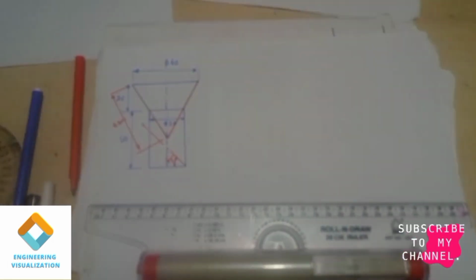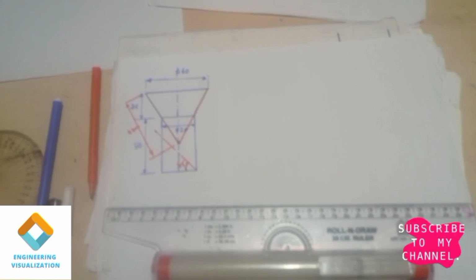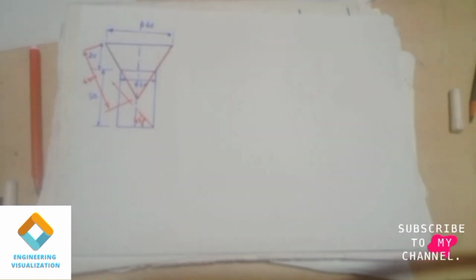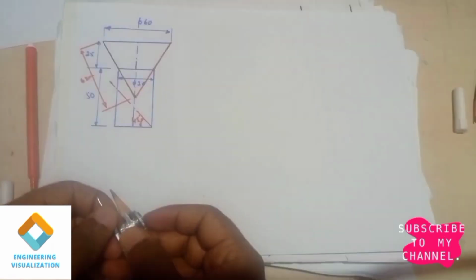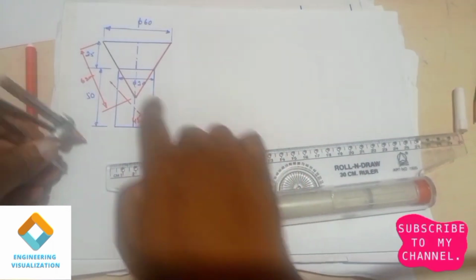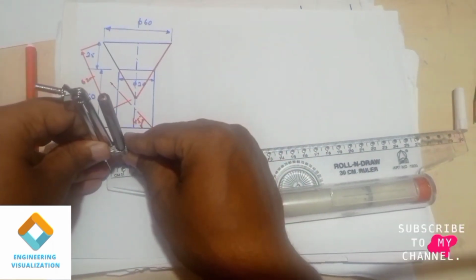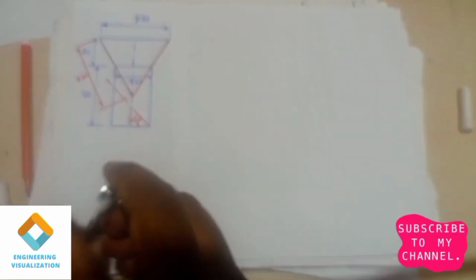So now we will be constructing the top view of the cylinder. Because in this problem the cylinder has been beveled. Beveled means cut, so that means we will be constructing only the top view of the cylinder. Here the cylinder has a diameter of 30, so I'll be taking the compass. The radius will be 15 mm. 15 mm means 1.5 centimeters, which we need to measure from the scale. Draw a circle.